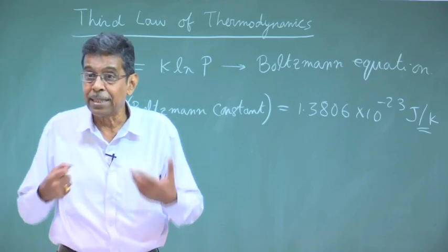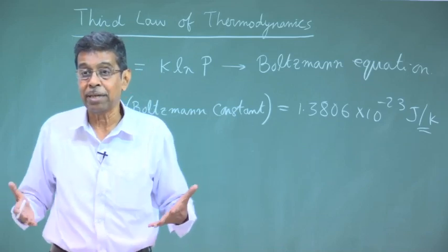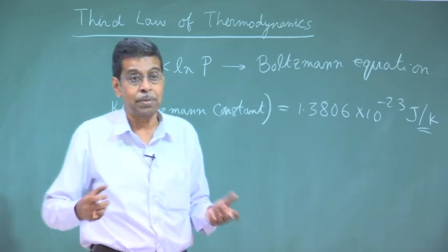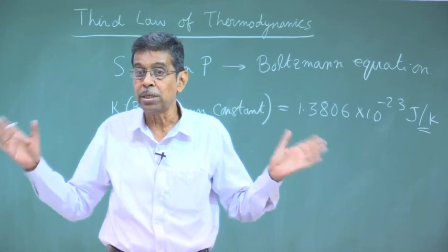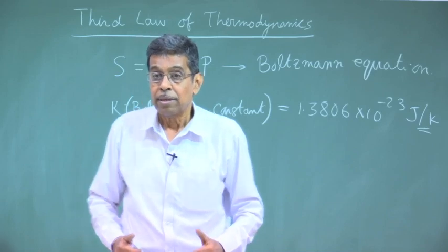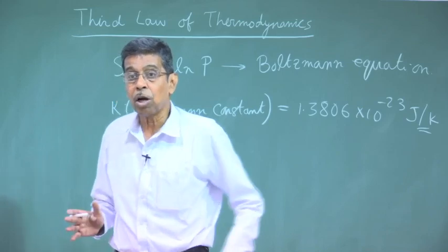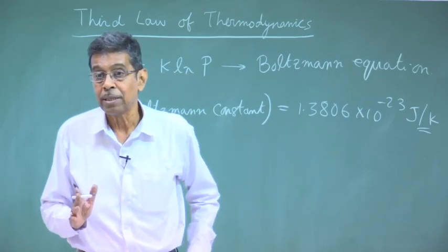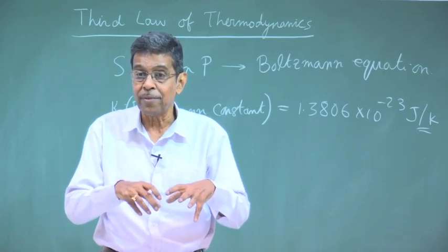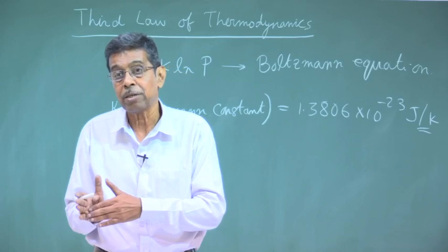Now there is another process to go for further cooling, which is adiabatic vaporization. That means if you have helium at 5 K and you make an adiabatic vaporization, the entire system is insulated, there is no heat transfer with the surroundings, and because of the vaporization the cooling effect takes place. Okay. So this is another way to go for further cooling. Another way of cooling a system is by the magnetocaloric effect. This effect is not known much. On a paramagnetic substance, by decreasing the magnetic field adiabatically, we can change the temperature to a very low value.